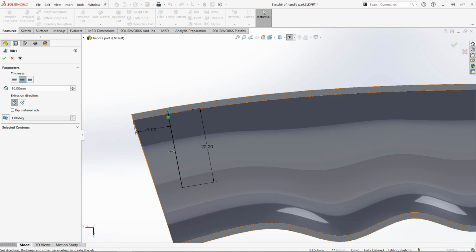So the thickness of these ribs I'm going to set thinner than the outer wall, so I'm going to set them at 0.8 millimeters. And then I'm still not getting a preview here, so I want to click on this option, and again all of these various options are pictured clearly in the PDF document. So if you are confused at any point, if you just really study the screenshots, you will see certain options are ticked or switched on. So it's this option here.